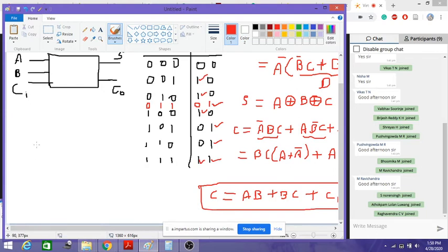So now if we write the circuit here, I'll try to write this with a 2 input XOR gate. If this is my A and B, then I can combine this with one more input here, that is Cin. So I'll get this as output. So this is my sum. Now the remaining terms are the basic AND operations.